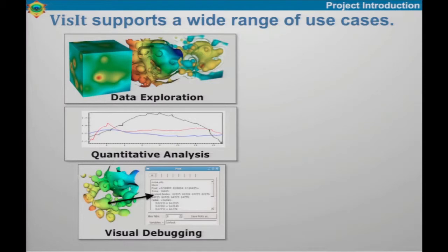And so we have a lot of functionality built in the tool to debug your data set, to say, at this location, these are the values, and we actually try to put it back into the notation, the terminology of your mesh, right? At this cell, at these points, these are the values, these are the neighboring cells, to give you all the information you need so you can actually figure out what went wrong. So we have a lot of cool debugging information there, and I'll show that off in the demo.